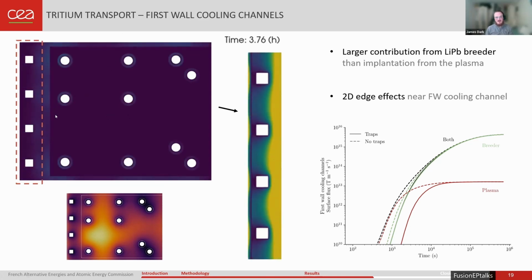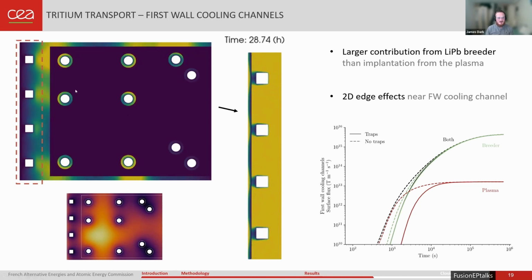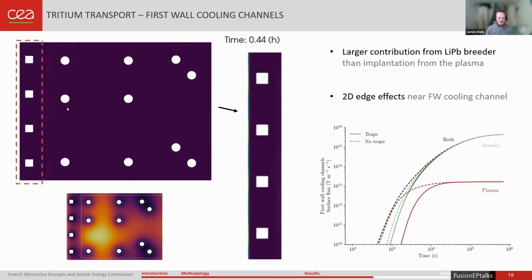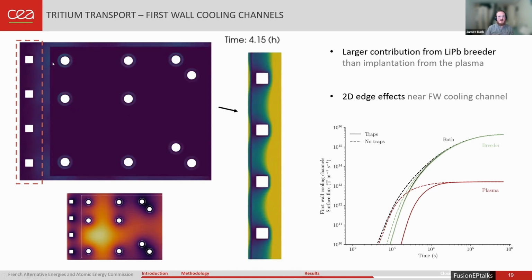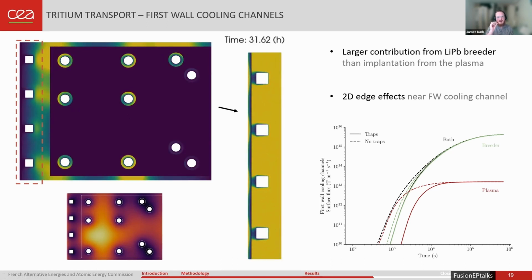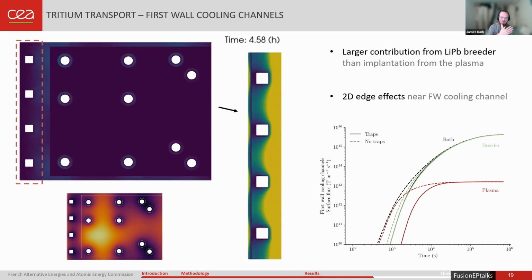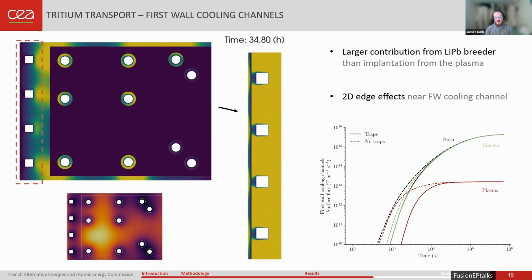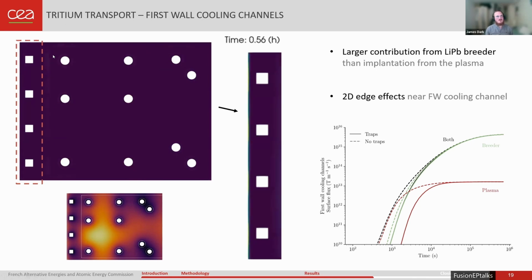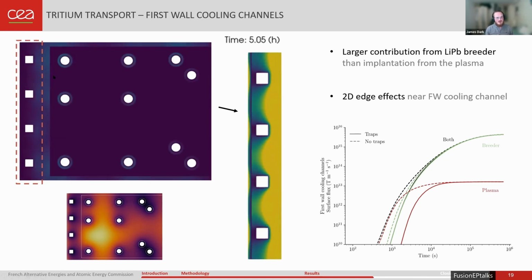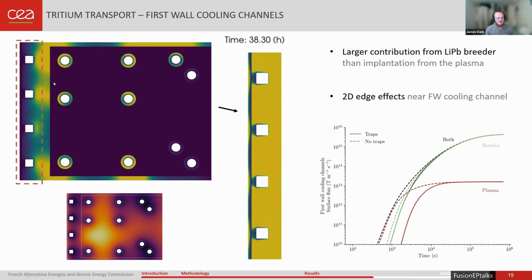Permeation barriers. So the idea is that you're essentially on the outside surface of your, or potentially on both of your surfaces, you'd either spray on or basically have a material that's a few micrometers thick that would try and mitigate as much permeation as possible. This could be a material such as aluminium oxide. I think there's been a few other suggestions.